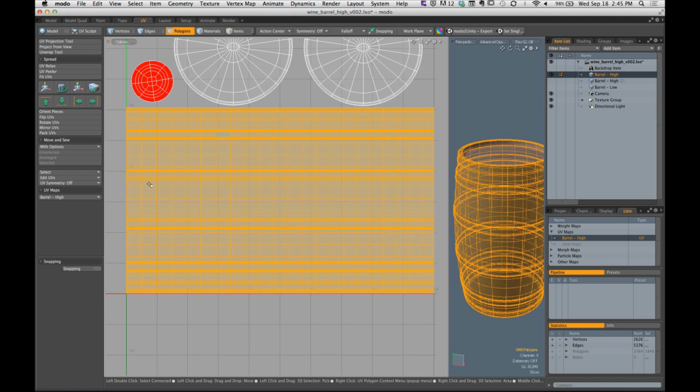Yeah, Waddell, what's up? Okay, when I'm trying to fix my UV, I'm trying to fix the line of my UV, and right now I'm working on the size of the UV. When I tell it to go to the left or right, it completely overlaps the whole UV. Show me. Yeah, okay. That makes sense because you're doing up and down, right? Now, also, look at what is selected on your UV. You get both edges selected, the topmost one and the bottommost one. Deselect the other one.